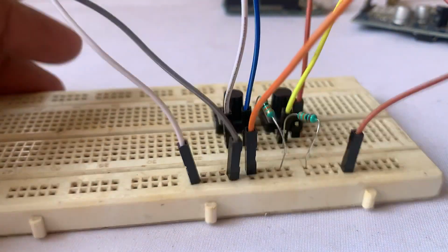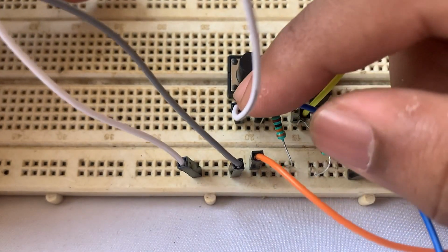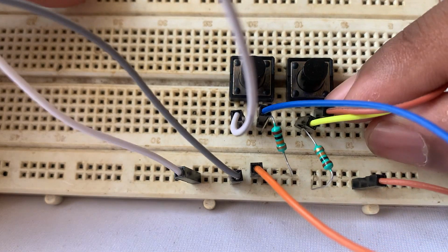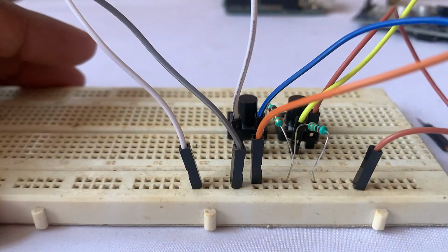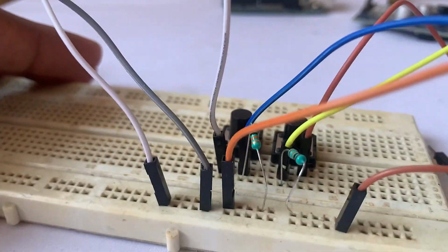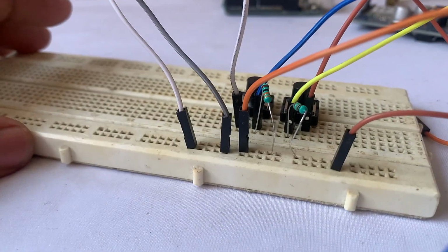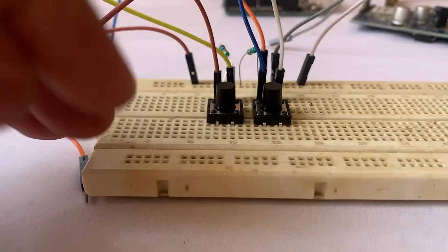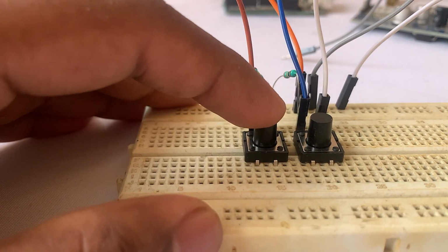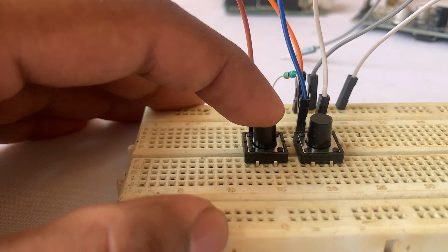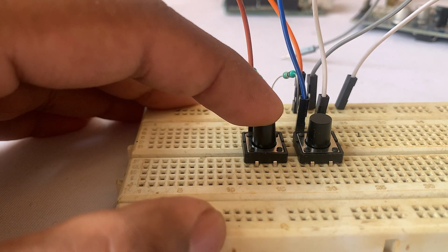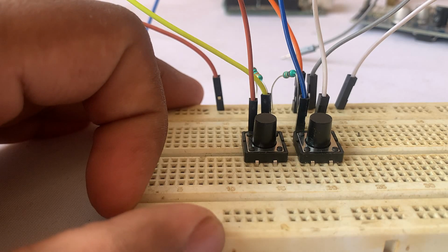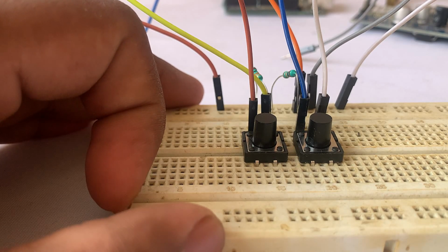And regarding the other 2 terminals, that is the white terminal in this push button and the brown terminal in this push button, they are connected to ground of the circuit. Since we are using the push buttons in pull up logic, I have connected the free end of the push buttons to ground of the circuit. So now what happens is, as per my explanation in the previous video, whenever I press the push button I will be receiving 0 volt signal in the digital pins of Arduino UNO, and when I release the push button I will be receiving 5 volt signal or high signal in the digital pins of the microcontroller.